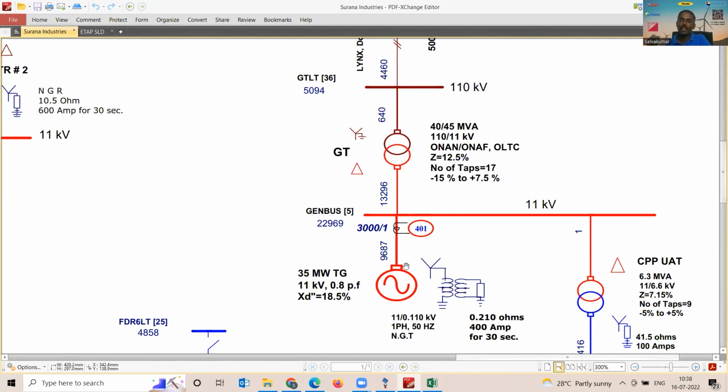This means we couldn't convert the entire chemical energy of the coal into heat and then into electricity. Out of 100 kilojoules or kilocalories per second or minute that I am dumping into the coal bunker, I am getting only 35% or 32% as electricity. The remainder is predominantly wasted as heat. That heat could be used for a process.